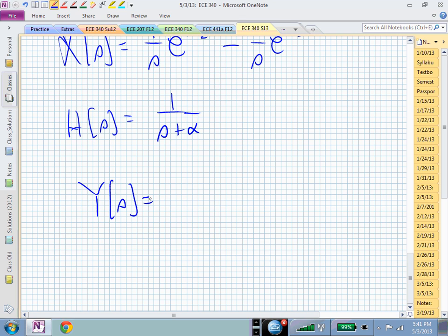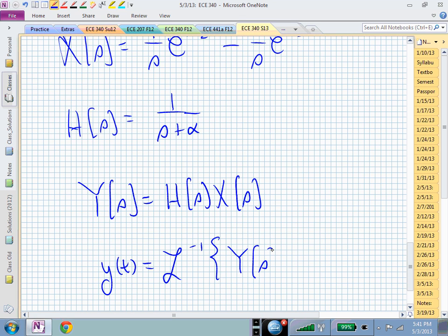Again, going back to the very first picture, you now know that the product of transforms in the S domain gives you the Laplace transformed output, and if you needed that in the time domain, you need to know how to perform this inverse Laplace transform, which if it's polynomials, you can now find the roots and just do the partial fraction expansion to obtain that y of t.